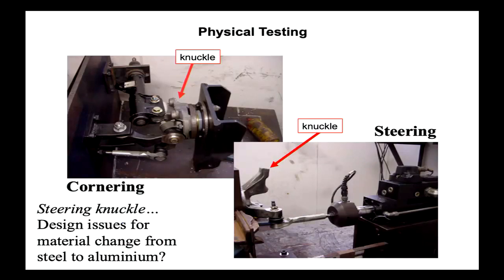We also had to think about the existing testing regime. Automotive manufacture is not as tightly controlled as aerospace, but it's still pretty tightly controlled. We had to have 10 to the 8 cycles, so 10 to the power 8 cycles, and still not have any evidence of cracks. And every so often, we had to take it off the fatigue tester and put it onto other testing devices that would simulate, say, a wheel bumping roughly into a curb or going through a pretty deep pothole. So that was the process. And so we got a successful outcome.